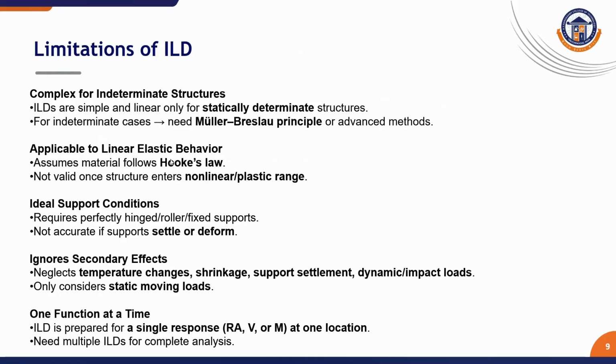An influence diagram is drawn for one specific function at one specific location. A complete analysis requires a family of these diagrams. The analysis does not account for the dynamic amplification effect of moving loads.